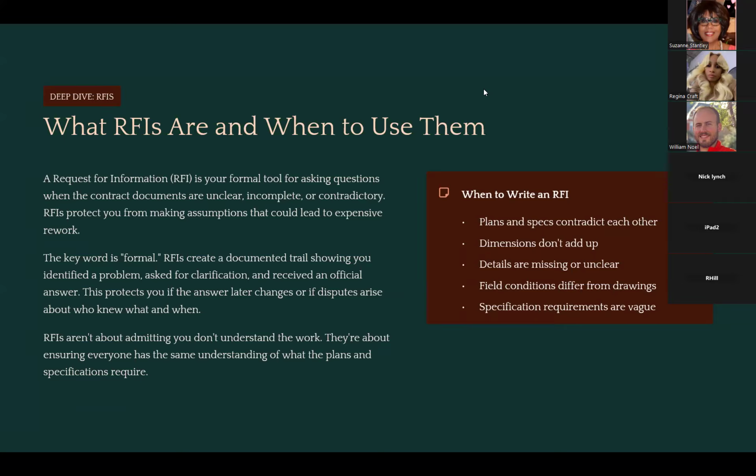And a good architect is going to provide an updated drawing. And if it changes what you are providing, then the general contractor will send it to you and say, hey, here's a change in the contractual documents, and let me know if you have any change in cost. And you're going to review that. A lot of times that is called an ASI, which stands for Architect's Supplemental Instructions. And you're going to look at that and say, yep, my toilet paper holder is different. And now the one I have to provide actually costs $50 more per unit, and it takes 6 weeks to get.